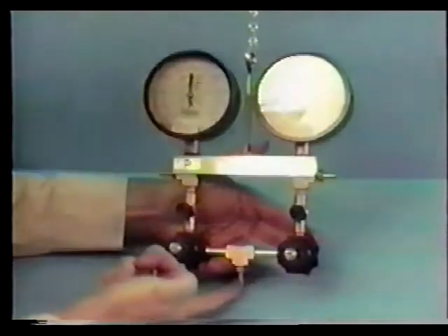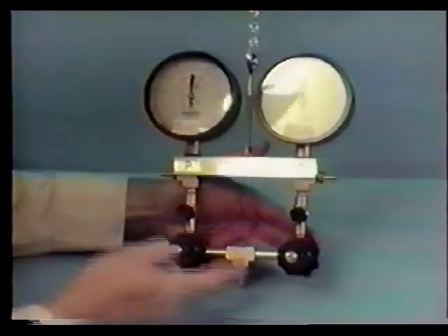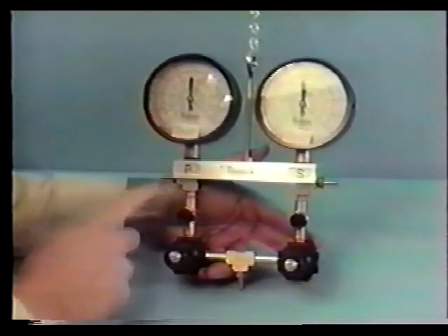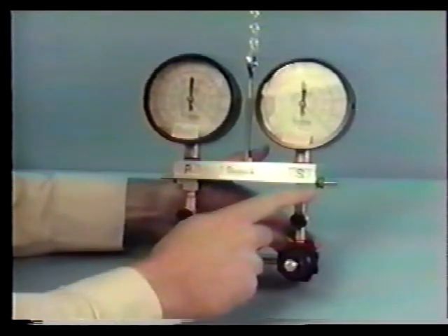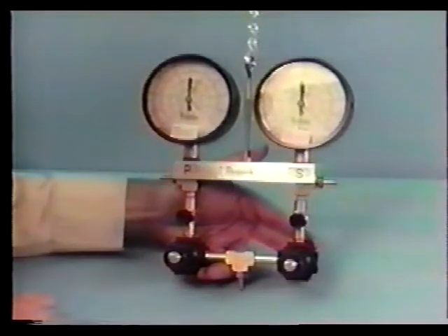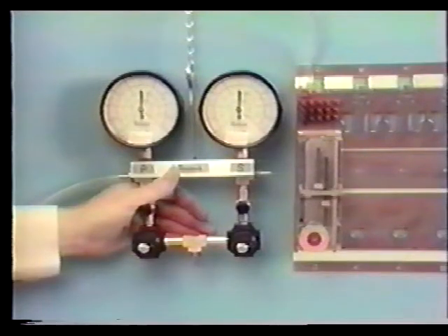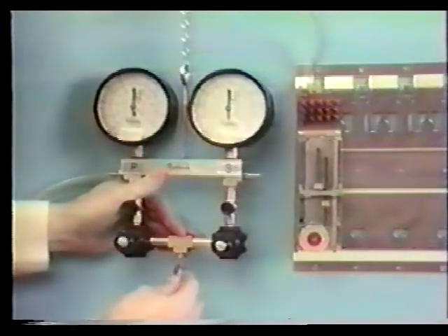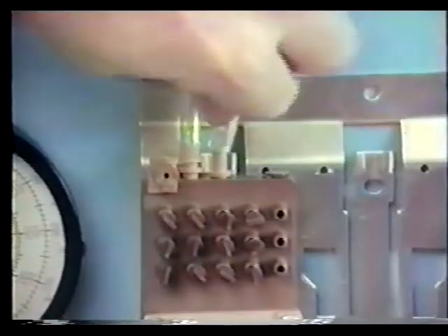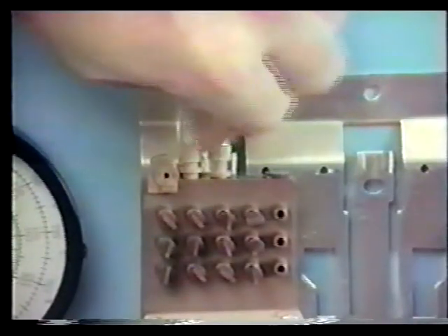A main air input is applied here, and the simulated transmitter outputs to the receiver controller are attached here at the P port for the primary sensor and here at the S port for the secondary sensor. We will be using only the primary signal for the single input calibration. We need to connect main air to our calibration gauges and to the receiver controller, and connect the primary output of gauges to the primary signal port of the receiver controller.